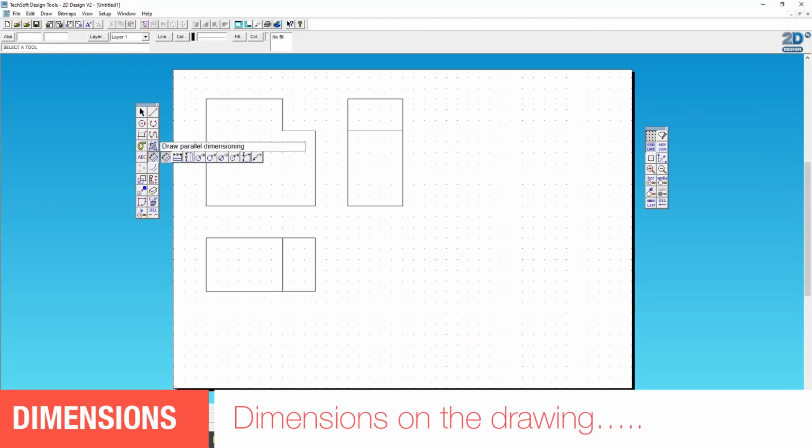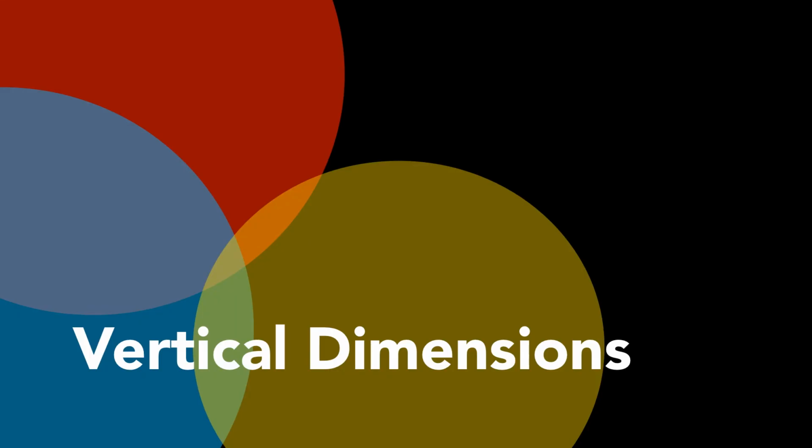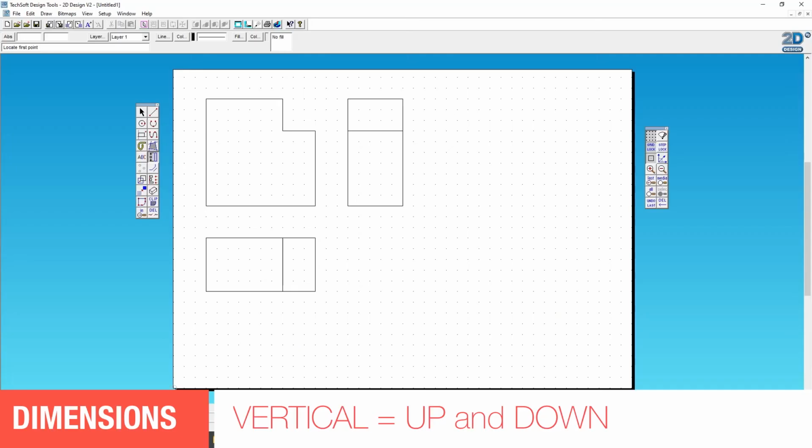Now we are going to add dimensions. Dimensions can be horizontal or vertical. We're going to add the vertical ones first. These go up and down. You will need to make sure the attach tool on the right hand menu is on for your dimensions to attach to your drawing.